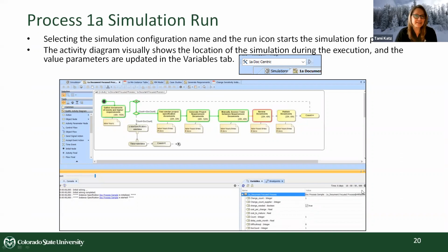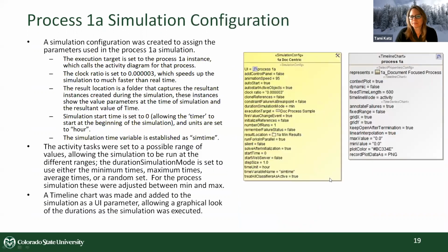Now, one of the things that was a challenge for me as I was running this the very first time was I didn't realize to set the start time to 0. It has a running clock, so if you don't set start time to 0, when it starts your simulation, it just picks up wherever you're at on your PC clock and runs through. So you have to normalize that start time and tell it what units you want it to measure in and what steps.